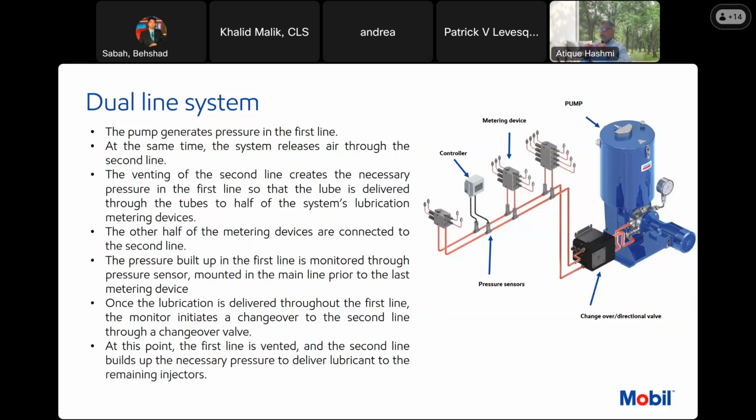So everything has to be considered when deciding what type of lubricant you are using, how far you are dispensing, what pipe diameter you will be selecting, what type of fitting you would be selecting, if you even need a fitting, or you can just curve the pipe and get it to flow. Because if you have a T, it will reduce pressure more than if you have a curve or a bend in your pipe. Everything needs to be calculated before you decide.